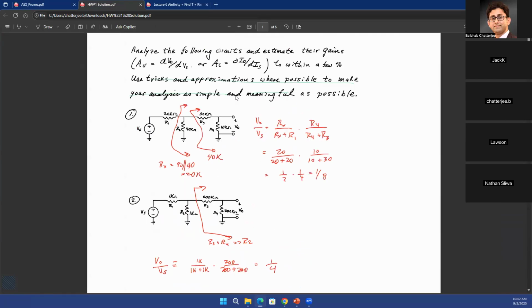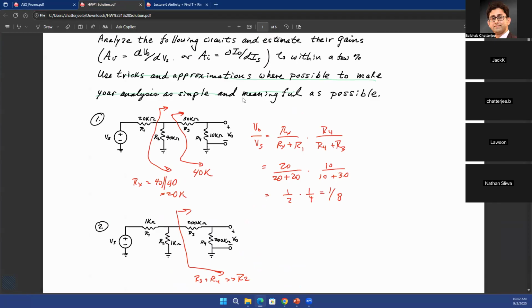Of course, the solutions to the first three problems I'll post right after this class today. However, I'm solving them the way that we discussed in the class, using voltage divisions, current divisions, and so on. I guess the first problem was pretty straightforward. Again, you have to work your way backwards from the output side toward the input and find the effective impedances that you see looking into the network.